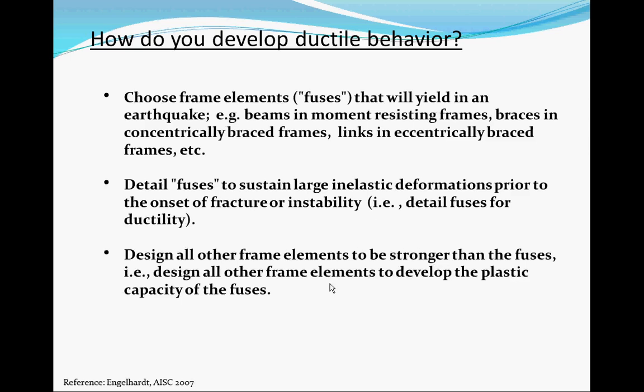In concrete, I think it's very, very similar. They force you to do the plastic hinge first, figure out how much strength you have, then you design around it. And in concrete, detailing is what most of the stuff that comes into play.